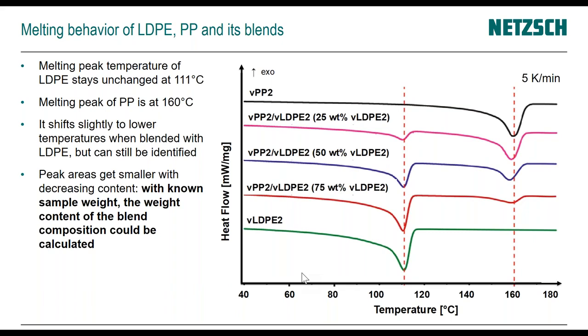The temperatures that can be achieved with the rheometer, we go up to 450 degrees C, and with the capillary rheometer that could also be used even a little higher. So you can analyze materials like high temperature, high performance materials like polyether ether ketone.